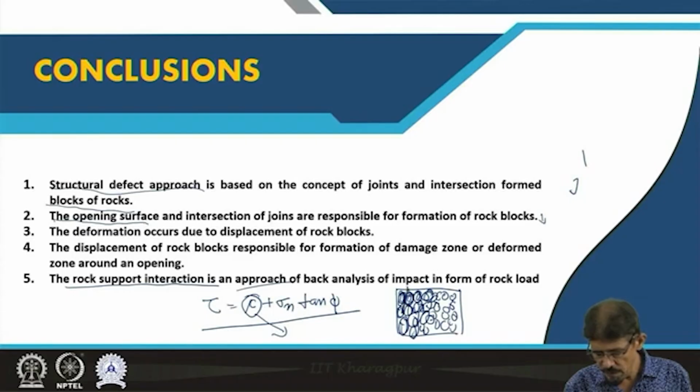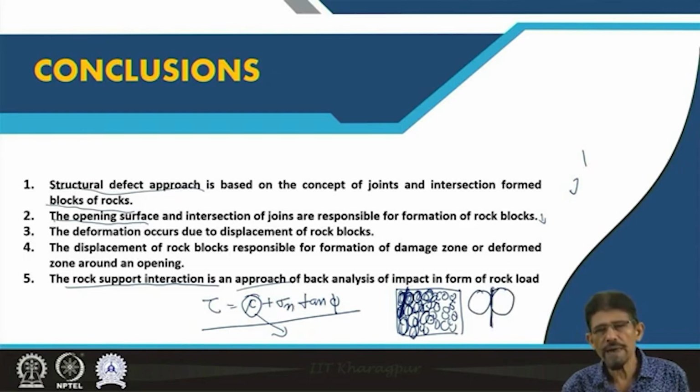If the forces or stress acting between two grains are less, like in the case of sand, where the grains are almost detached from each other or simply in contact, showing very little or close to zero stress or binding condition, then in the case of sand this C should be close to zero.